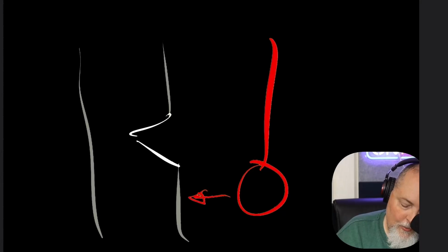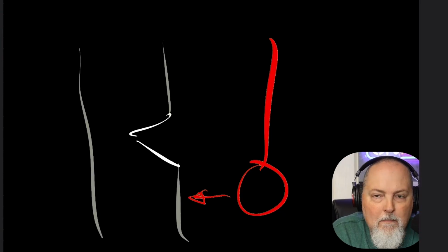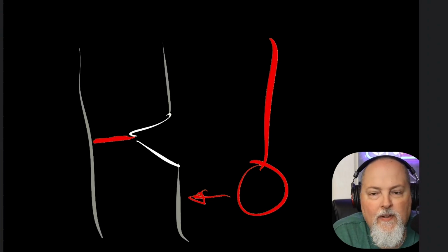And so I guess I should have drawn that vertical. So imagine this, let's just draw vertical, put a V in it. And then over here, I've got a big pendulum swinging, and it swings into the material. So this is used to measure impact toughness, the amount of energy a material can absorb before fracturing. So they're going to be looking at this structure right here. And what they want to see is they strike this with a swinging pendulum. The energy absorbed before the fracture is measured as impact toughness.